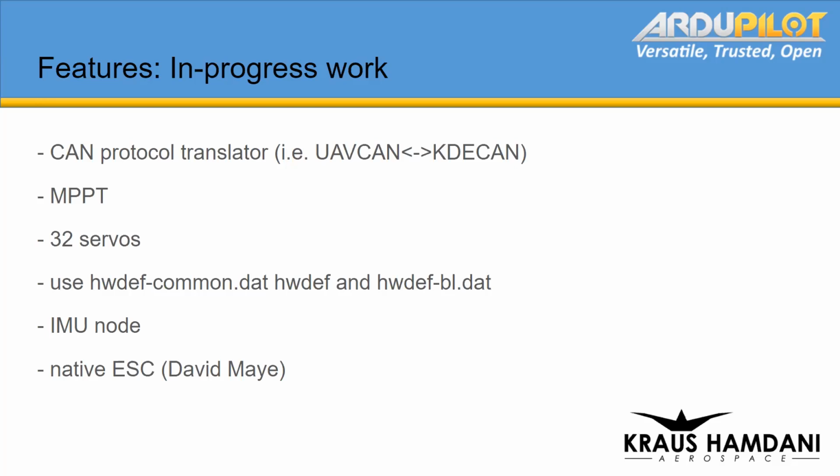Native ESC, yeah. David May is a new hire here at Kraus Hamdani Aerospace, and he's working on an ESC as a standalone native device that's based on AP_Periph. So it would be adding a new feature to ArduPilot as an ESC. We'd have an open source ESC that can run our algorithms, but also run all of our infrastructure, UAVCAN, serial ports and feedback, and also act as a battery to measure currents and all that. So he's working on that, and really excited about that. So that'll be a big plus